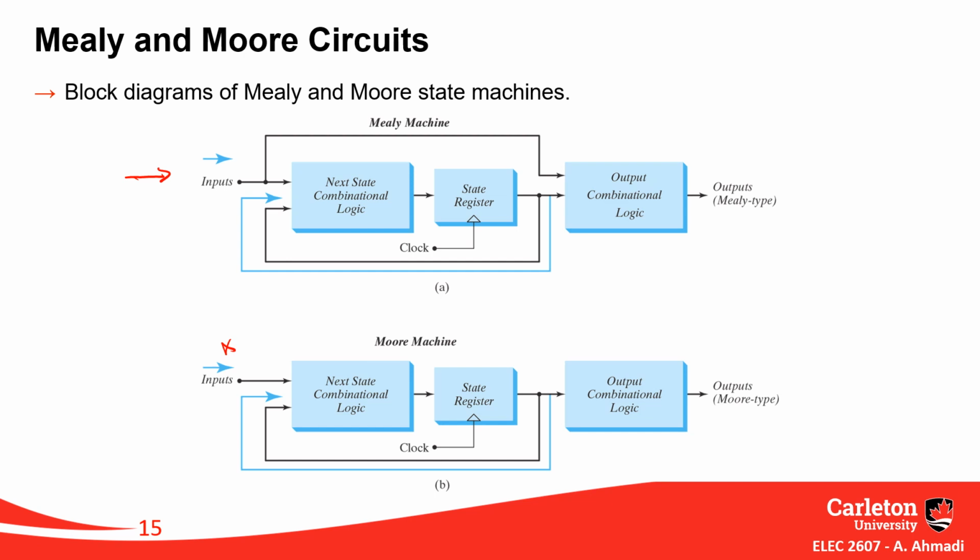Someone pushing a button, turning on and off, doing something coming from another circuit, which is not necessarily synchronized with your circuit. So it might be possible because there is a change in your input unsynchronized with your clock, output of your circuit will change because this input directly affects the output and states as well, right?